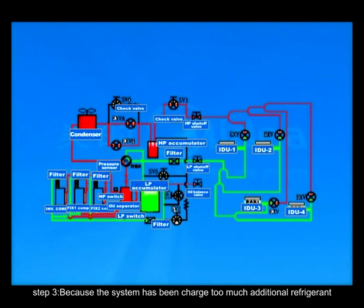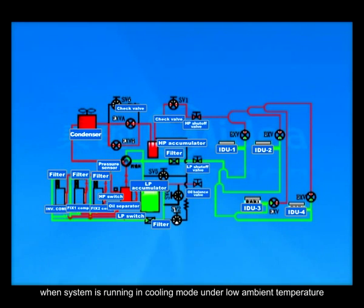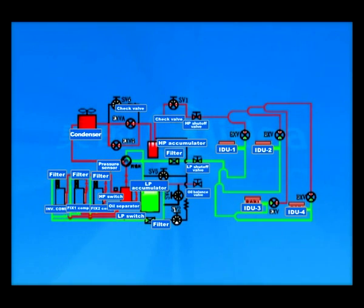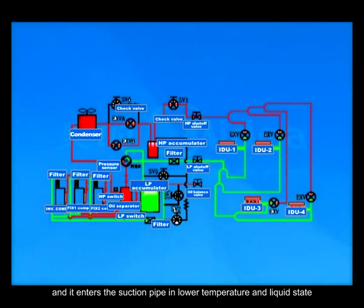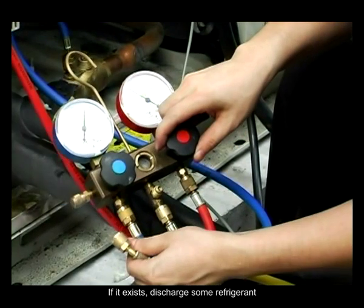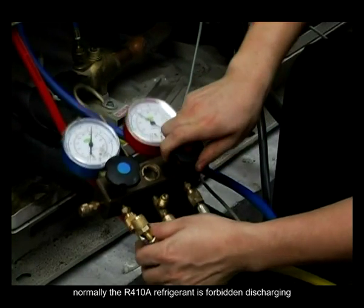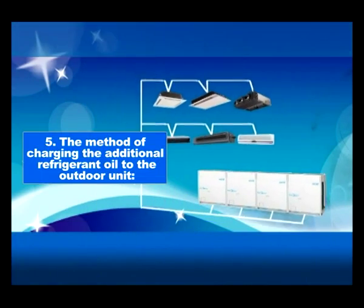Step 3. Because the system has been charged with too much additional refrigerant, when the system is running in cooling mode under low ambient temperature, there is much refrigerant in the indoor units that doesn't fully evaporate, and it enters the suction pipe at a lower temperature and in liquid state. If this exists, discharge some refrigerant. Normally, discharging R410A refrigerant is forbidden.